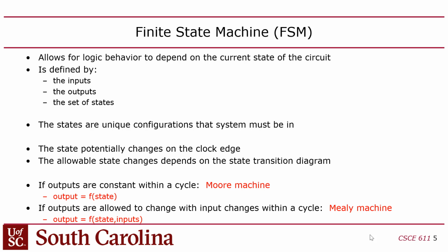Now there are some things in System Verilog, like you have to declare signals before you use them, but that's just a rule they made up in the language, right? But in general, your circuits are all operating concurrently. But what if you have to introduce some kind of sequential behavior in hardware? Like you need to have a sequence of things that happen over time, right?